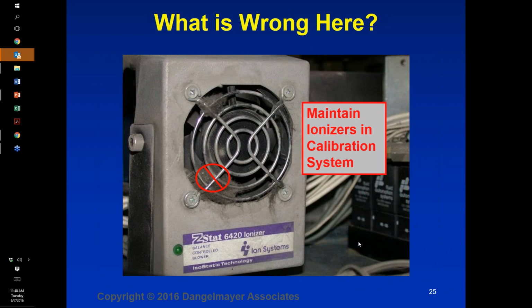The question is that they're raising the question about ozone being a problem. Okay. One of the things that you want to know about ozone is whether your ionizer is producing ozone or not, and that should be in the manufacturer's data sheet. Most of the ionizers that are used in sensitive applications produce very low levels of ozone. If you can smell ozone from an ionizer, it's too much. That is not an ionizer you want to be using.